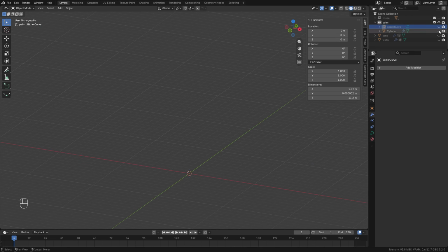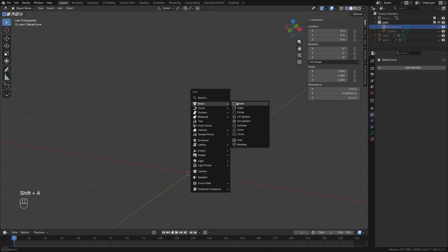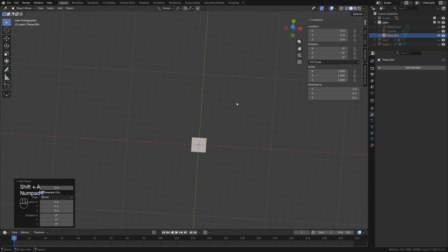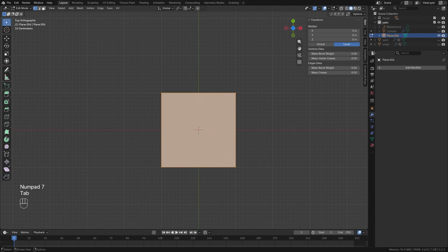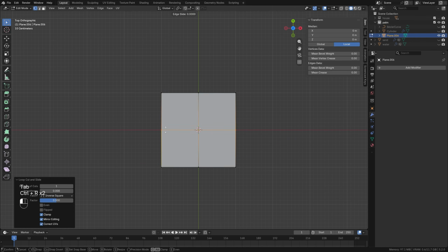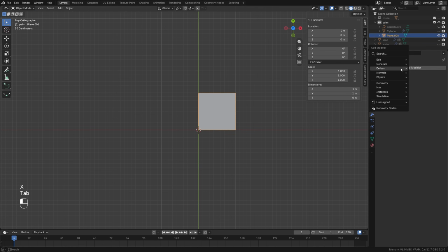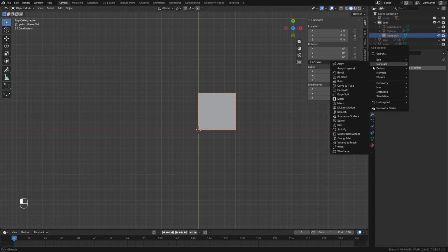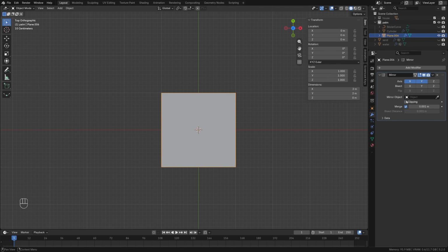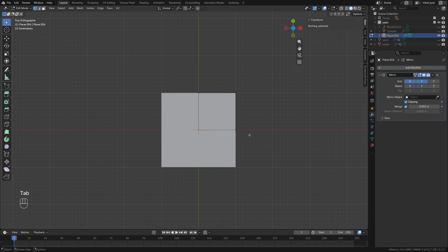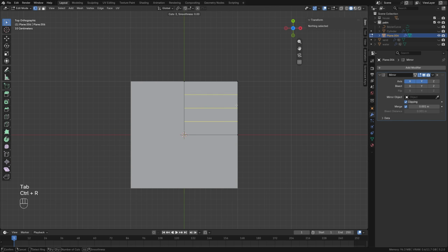Now we will create a leaf. We remove everything unnecessary again. We add a plane into the scene. We will switch to top view and in edit mode, subdivide it vertically and horizontally. And now we will delete 3/4 and restore the shape using the mirror modifier along the X and Y axes with the clipping option. In edit mode here, we will add 3 cuts, turn on the move tool.